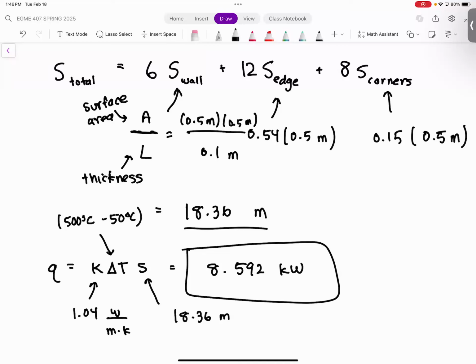Any questions on this here? Yeah. So Kelvin and Celsius are kind of interchangeable. You can use one or the other. Watts per meter Kelvin, or Kelvin and degrees C, is kind of interchangeable, so you can replace this with degrees Celsius. That's usually what I do for thermal conductivity, but for some reason my notes have it the other way. But degrees Celsius and Kelvin are interchangeable in this situation. No, because Kelvin is just a constant offset, so there's no multiplication when you convert from degrees Celsius to Kelvin. So the units for thermal conductivity and stuff stay the same.